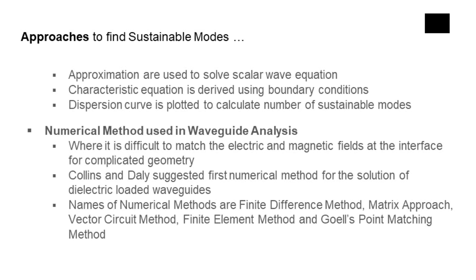Although there are several methods which have the advantage of only requiring the solution of a small matrix eigenvalue problem, each of the trial functions is limited to a particular geometry and requires the evaluation of lengthy analytic expressions. A method of approximating a function space that does not suffer from these difficulties is the finite element method. This method is commonly used for heat and fluid flow problems and for complicated electromagnetic problems. In this method, the region of interest is divided into triangular elements and a polynomial approximation is made of the function in each triangle.